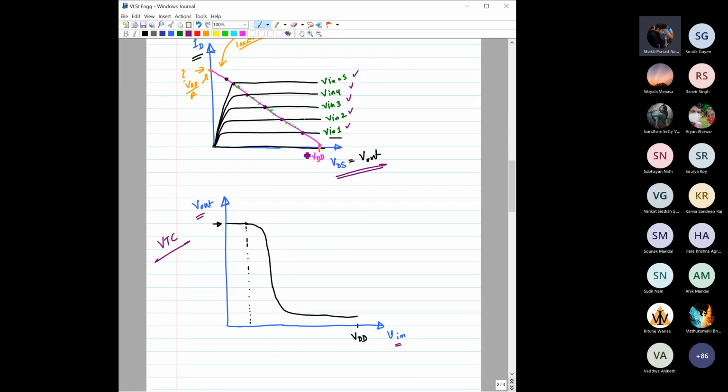So from that, you know that, right? Until and unless we reach this, say, VTHN, the threshold voltage of this NMOS, the current would be 0, and the output voltage would be constant at, please tell me, VDD. VDD only. Okay, so till VTN. After that, what will happen?